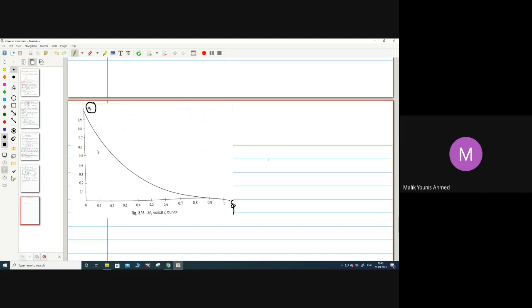But make sure that the damping you increase stays within a specified value, as recommended by the manufacturer or the plant guidelines. Because if you keep on increasing the damping, the response will become slower. You have to draw a line where you increase the damping enough to decrease the oscillations.